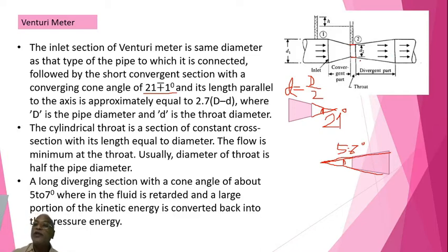So that's why to reach that same diameter D, it takes a longer distance, whereas this comes quite sharply. That is an interesting thing that one should remember. The flow can occur only in this direction. You cannot supply the flow this way, or change the direction of the Venturimeter and use it.